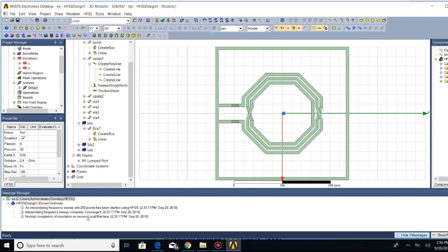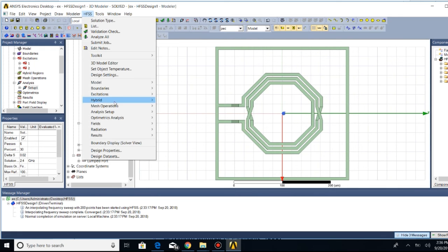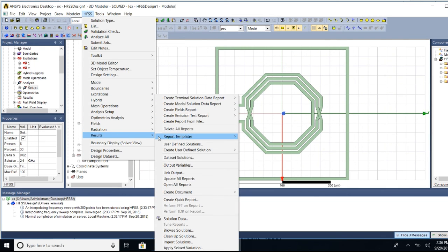We have got this output. Everything is fine. No error. We have to observe the inductance. Inductance, we have to add an output variable. So in HFSS we'll get only the parameters like S parameters and Y parameters. Using these parameters you should write an equation for inductance.